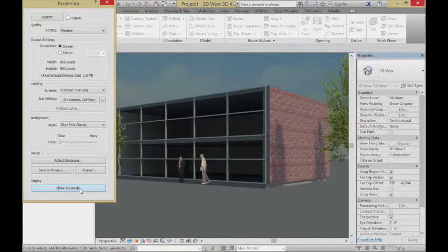But all we really did was take the volume of the room, height by width by length, multiplied together to figure out how many cubic feet are in the room. Then we say how many air changes per hour, 4 being the minimum, up to much higher. We figured out so many cubic feet had to move per hour, divide that by 60, and you finally get how many cubic feet per minute. If that number is 1,000 or 1,500 or whatever it is, we need to move that much air into the room and that much air out of the room, because we need to get them in balance with each other so that they're ventilating nicely.